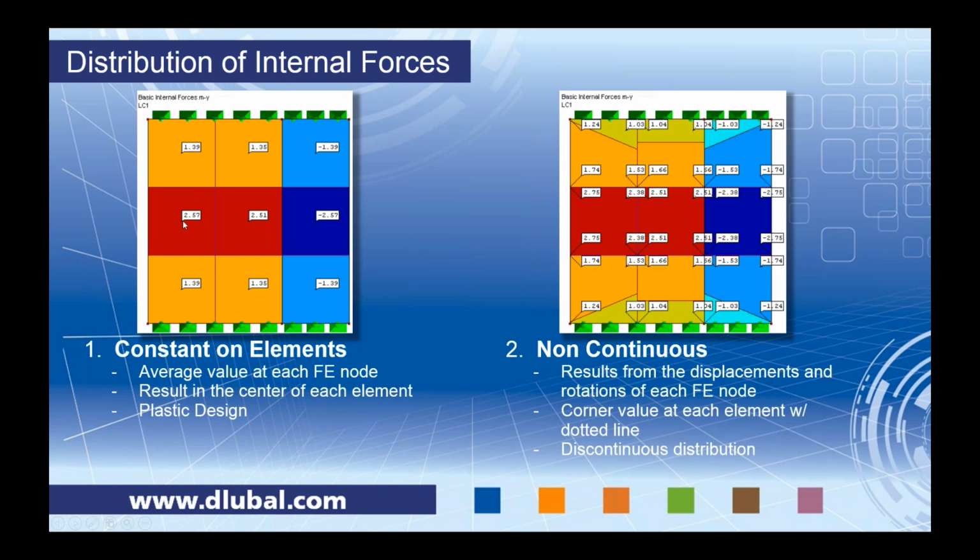If one of these adjacent elements exceeds 50 KSI, the same thing happens: the stiffness is reduced, and the load is further distributed to the other adjacent elements. This continues until we have a plastic effect for many of our elements, and the load is fully distributed.